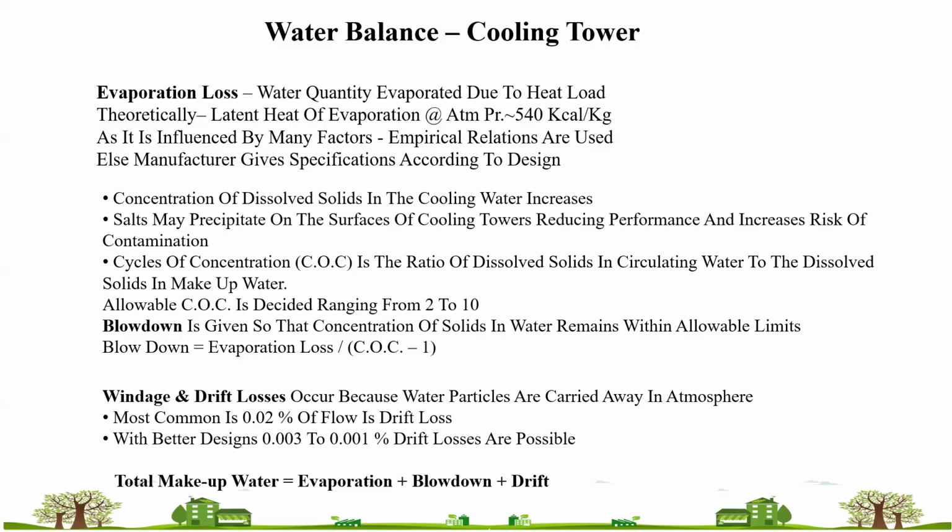Okay, sir. Yes. One more important parameter of the cooling tower is the water balance. What are the losses in water? There is only water loss in a cooling tower. Water loss means your water is getting evaporated. Then another loss is blowdown loss, or windage or drift losses.